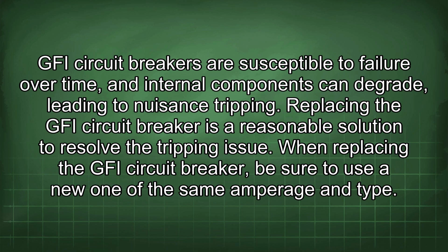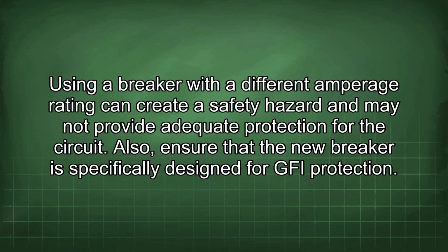When replacing the GFI circuit breaker, be sure to use a new one of the same amperage and type. Using a breaker with a different amperage rating can create a safety hazard and may not provide adequate protection for the circuit. Also, ensure that the new breaker is specifically designed for GFI protection.